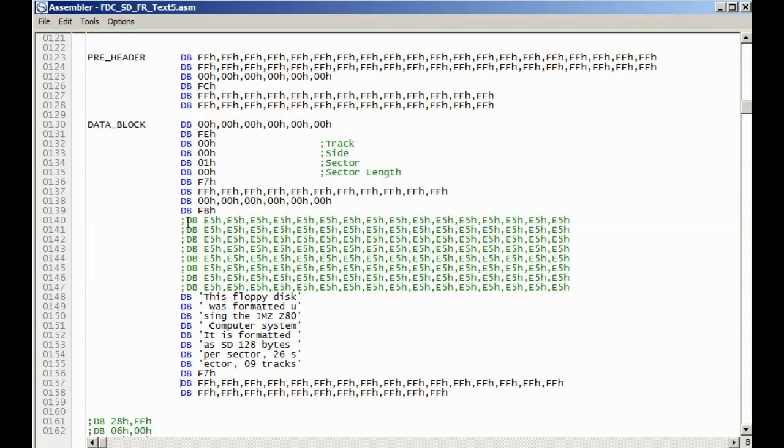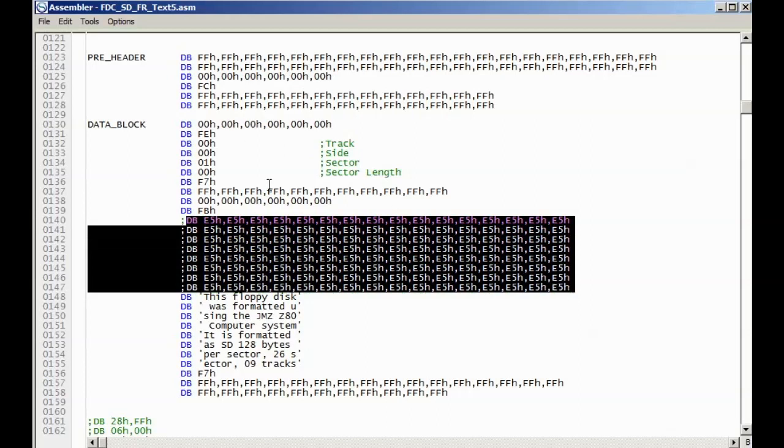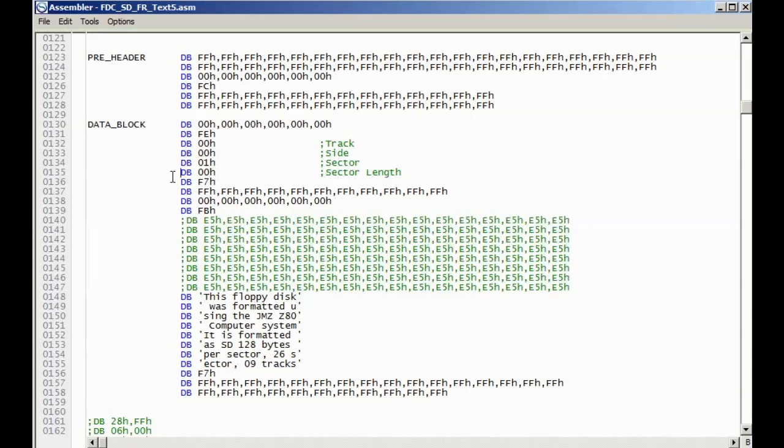The only bit that you normally get from the floppy drive controller when you try and read a sector is the actual payload. It doesn't normally return the rest of the data. That's just so that it can figure out what's going on. And it also makes it confusing when you don't get data back. It looks like the system's not working, but it may just be the track or side or sector or the checksum is wrong and doesn't match what you've told the system you're looking for.